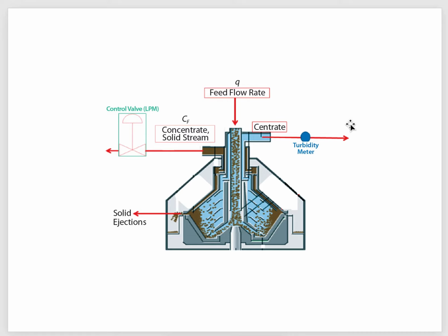So this is a continuous type centrifugation. How can we achieve this continuous working? There are some provisions, some outlet points, from which we can collect those solids which have been deposited here because of the centrifugal force. So usually in the industry, this kind of continuous high speed centrifuge machine is used because these are efficient, right?